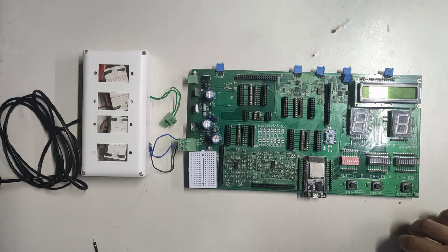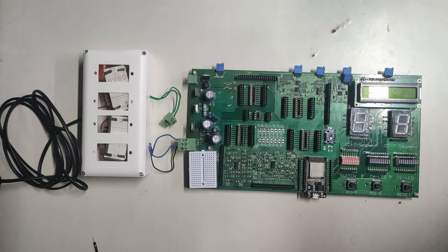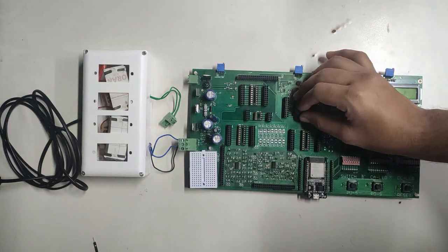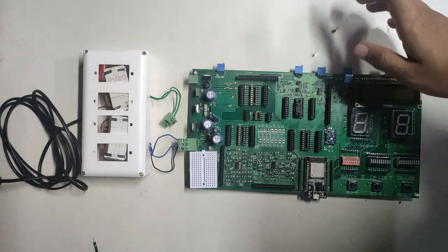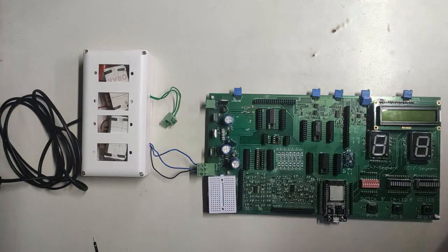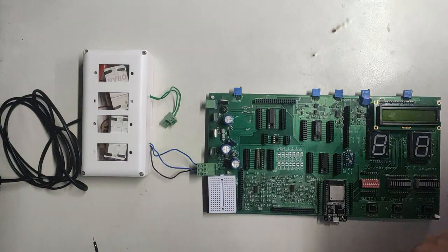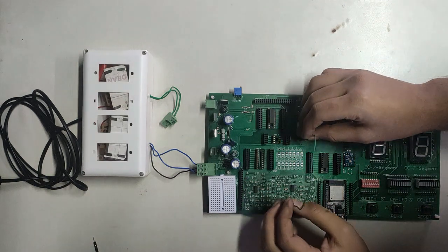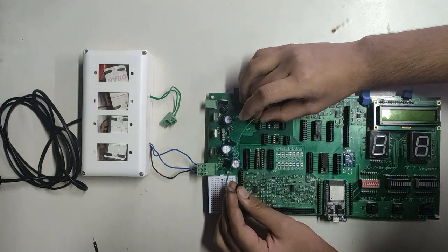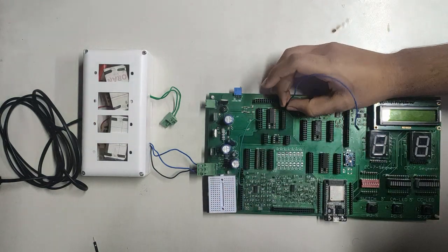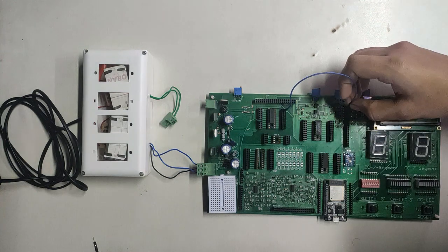So now we are implementing the full adder. To implement it, we will require three ICs, which is IC7486, which is XOR gate, IC7408, which is AND gate, and IC7432, which is OR gate. Now after implementing the ICs, now I am connecting the wires. So for all the ICs, the pin number 7 is common, which is ground, and pin number 14 is nothing but the plus VCC. So at first we are connecting it.